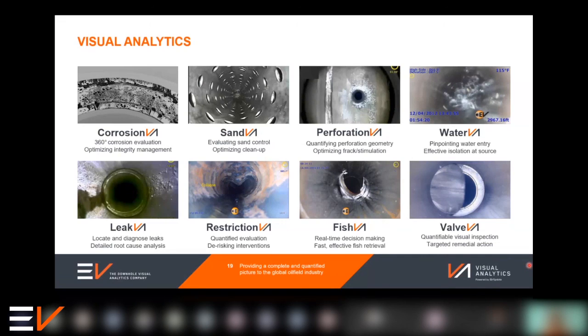The great thing about having the shroud, though, which comes with the kit, is it allows us to circulate clean fluids down the coil and deliver them right to the end of the camera. So if we're in an environment that maybe isn't perfectly clear, it could be turbid water, or it could be that there's oil there, you can circulate through the coil tubing, clean up the area of interest, and get a picture there. So it's a very simple operation for us. In the land environment, it's a guy with a truck with a pack of kit. We turn up and we utilize the best tools to fit the situation.